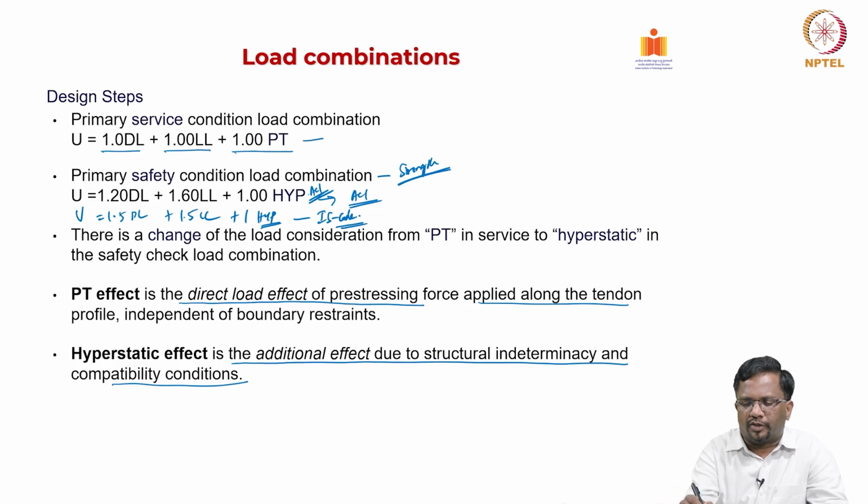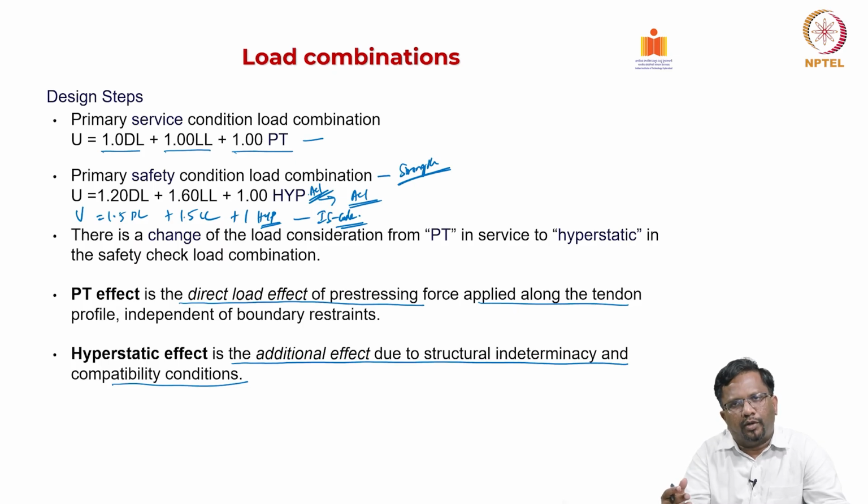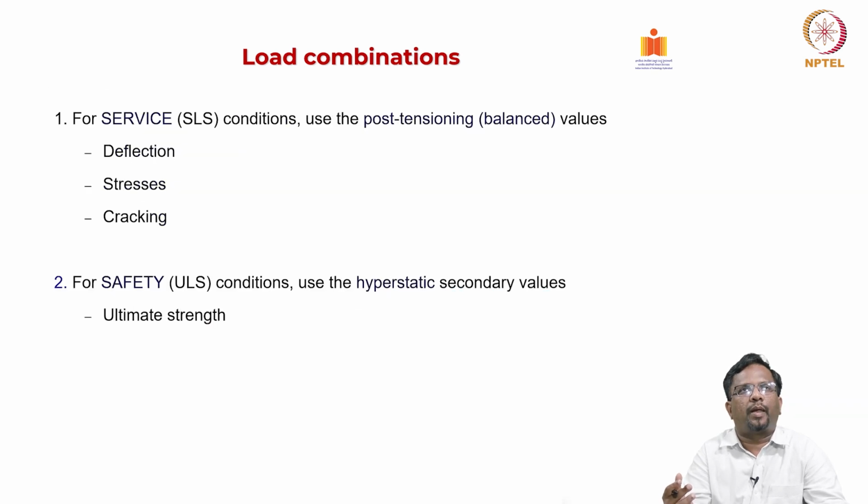And this is your service condition. So, these two conditions. Of course, if the amount of cable is not adequate, then I can also use TMT rebars or non-pre-stressed steel as an additional reinforcement for strength. That option is always there for the design engineer.